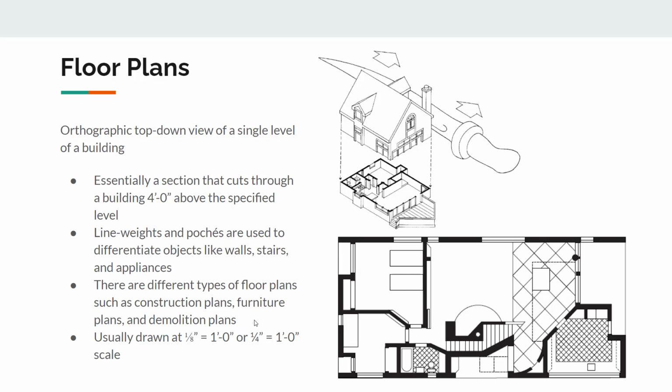So these are used a lot in renovations. And usually you'll draw the existing plan, and then you'll show things like walls that are to be demolished, and these will be represented with a dashed line or something instead of a solid fill like we're showing here. And then there are a bunch of other types which we'll get into later in the course, but just to summarize, these are 3 common types.